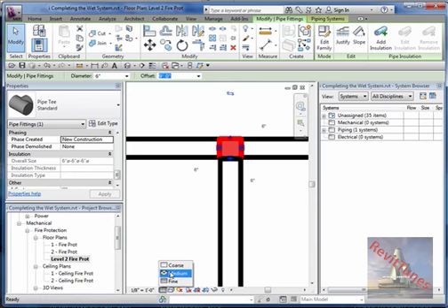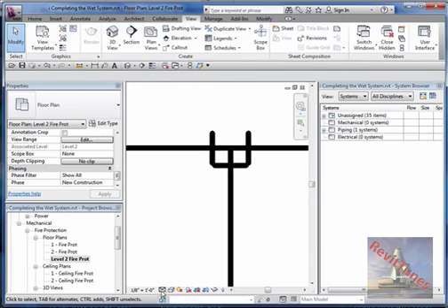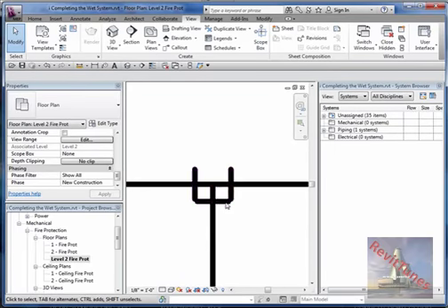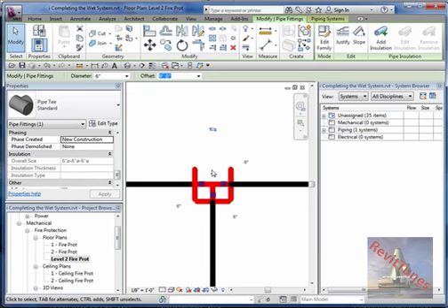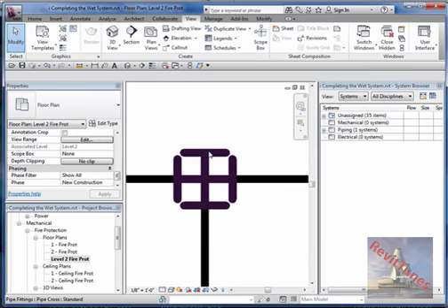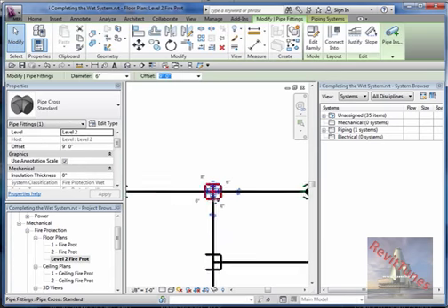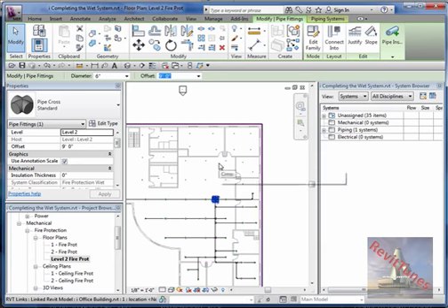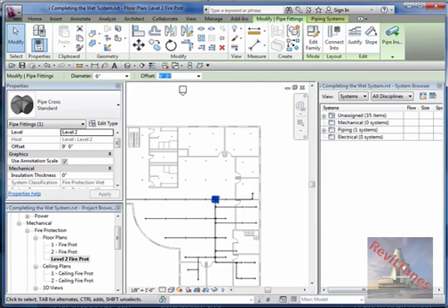If you go to medium view or coarse detail, you see it in 2D lines. Alright, so I highlight the T connector and click on the plus sign, so it gives me one more connector, as you see. Now from there my main line will continue and branches will distribute here to connect all these other sprinkler heads.